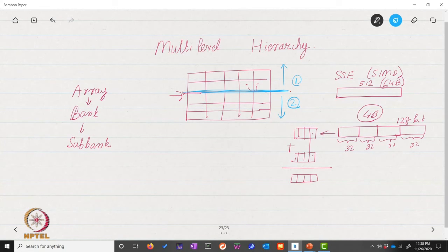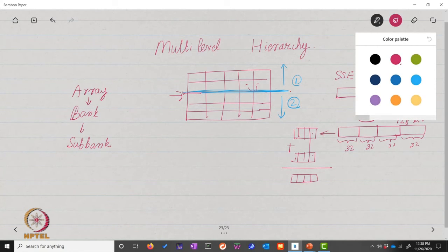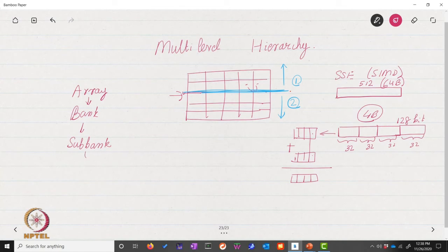So then this kind of simplifies the circuit a little bit, in the sense that immediately from the address we know where to go. Now within a sub-bank, we further divide it. So what Cacti does is that Cacti further divides a sub-bank into mats. Alright. So what is the advantage? The advantage of dividing a sub-bank into mats is like this, that let's say we divide it into 2 mats, right? So consider a sub-bank and let's divide it into 2 mats.